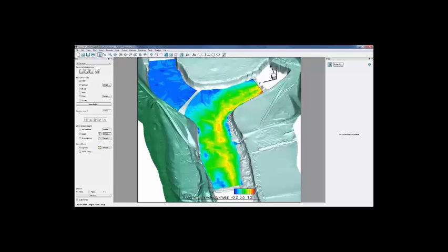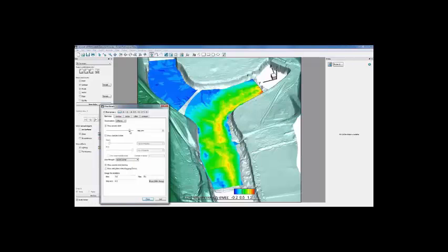In a lot of parts of the country, probably not at CJ Strike with the granite outcrops, but a lot of the country, we're worried about scour of bed material. And we have the data here with this very complete velocity and depth data set. We have the data needed to calculate a shear stress along the bed. So now I can take and put together a map just like this and start to look at where am I going to have issues of scour of sediment, of bed material. Where am I going to have issues of deposition of suspended sediment?